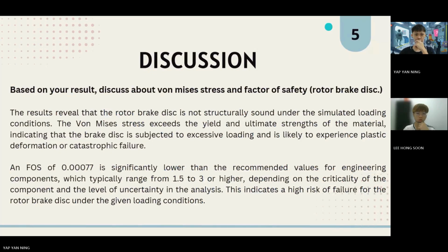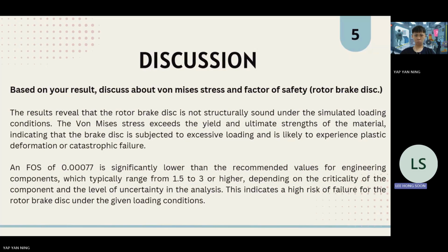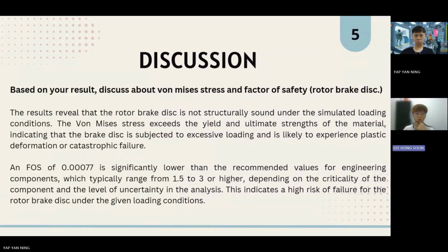Next, for the discussion, based on our result, we discuss von Mises stress and factor of safety. The result revealed that the rotor brake is not structurally sound under the simulated loading condition. The von Mises stress exceeds the yield and ultimate strength of the material, indicating that the disc is subject to excessive loading and is likely to experience plastic deformation or catastrophic failure.